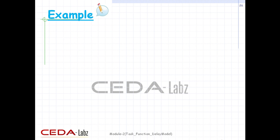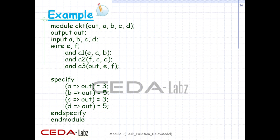Here is a Verilog description of an example for parallel connection. As usual, we started with module and module name followed by port list. These are the port declarations, out declared as output port, and A, B, C, and D are declared as input ports. Internal connections, E and F, are declared as wires. Here are the gate instantiations according to the figure in the slide 23. And, here in specify block, we specified path-to-path delays between input and output ports via parallel connection.